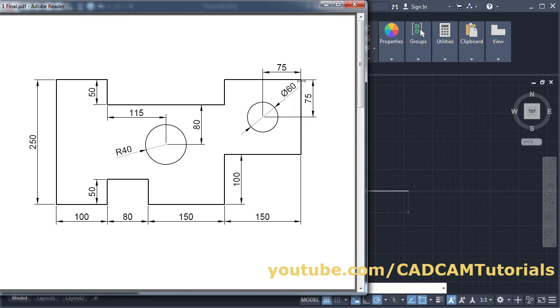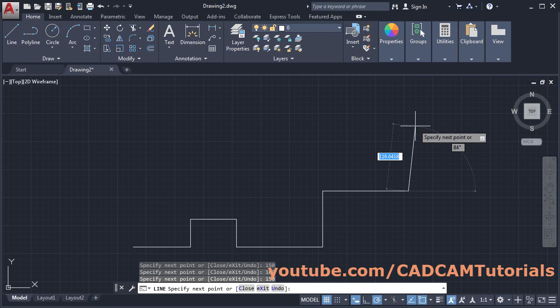Then this vertical length is not given, but we know this is 100 and this total length is 250. That means this length will be this 250 minus this 100, that is 150, and again this length is 150 and this is 50. Take it above, give the length of 150, enter.